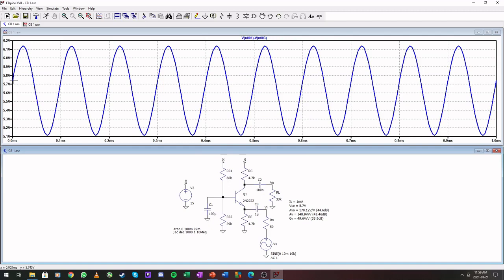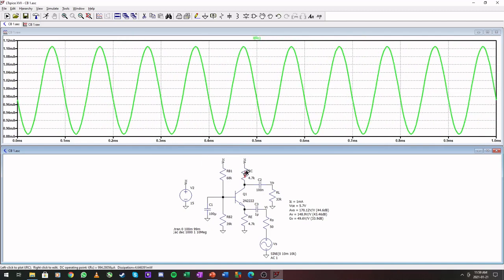Okay, so still at roughly 5.7 volts and this is still roughly at 1 milliampere. So this was the same as the first common emitter problem that we had. So we don't have to look at the bias anymore. We know that the bias analysis is kind of accurate.